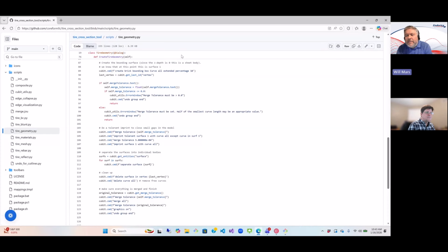Thank you very much. We've got a bunch of questions here. The next question is, can you comment on Cubit tools for tire tread meshing? Actually, the next couple of questions are all around that. What you showed us was all 2D. Can Cubit do 3D? Cubit can do 3D. I have done 3D tire tread meshes, and Cubit handles the sipes very well, for example.